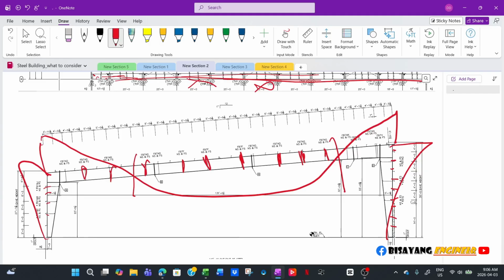So within this area, I mean, you still need bracing at that area, but not the same as in this region here, because the bracing is helpful for your compression member. For example, in this area you have positive bending, so your compression will be the top flange, but you have the deck already.